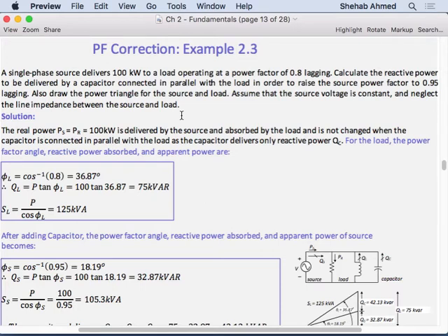We said that flux is basically an indication of reactive power, or flux is resembled as a circuit element as an inductor, which means we have reactive power. So reactive power will not change. The load did not change. Your motor is supplying the same load. It's requiring the same amount of reactive power to link the stator and the rotor. The transformer is the same. It's supplying the same load, requiring the same amount of reactive power.